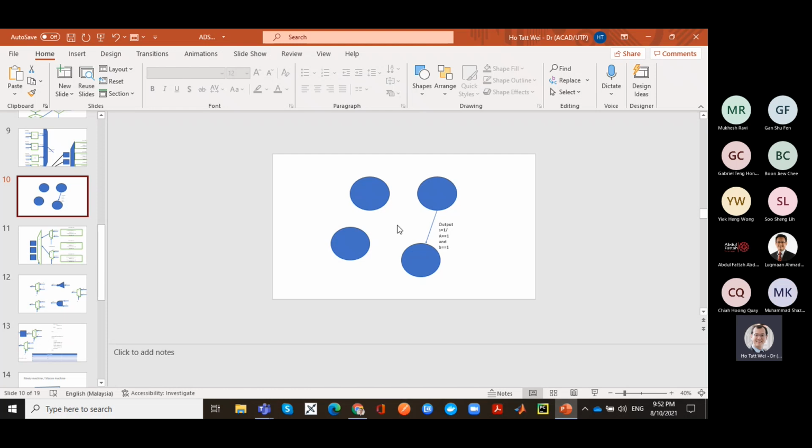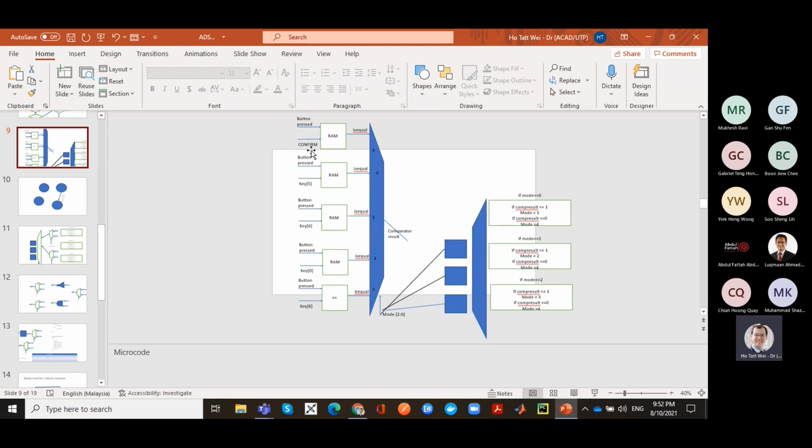But if somehow I can implement different state transition diagrams, different state transition combinations, I can sell more chips because these chips could be used in different cars and all that, right? So that's the idea of FPGAs. You actually can sell many more of them because you can program them. What you're doing is specifying a different lookup table, a different combinational logic function, up to what you want, in order to perform different types of computation, right? So that's why FPGAs are a good market, because they don't just sell in one particular domain. They can sell in any kind of application because of the programmability.